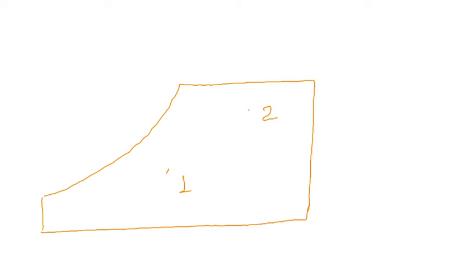Just horizontally, it has to be a horizontal line. We'll draw this. Okay, so let us say this is your state 1 to 2. I am interested in knowing where would be the position of state 3 on the psychrometric chart. So this is your state 1, means this is the room here, and this is your outside or fresh air.